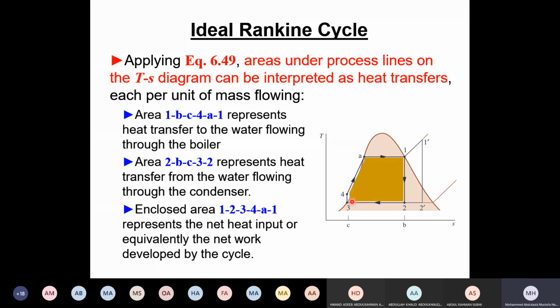And therefore, 1 minus QL over QH, the area, will give me the efficiency, or it is W over W plus QL, which is actually QH. So the area here is QL, and this area is the work. Work plus QL will give me QH, and therefore eta is equal to W over QH, which is all of this area.